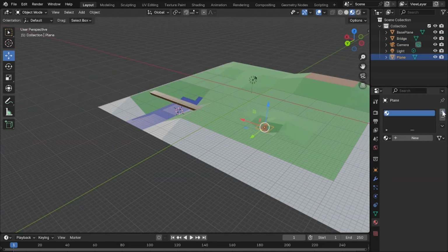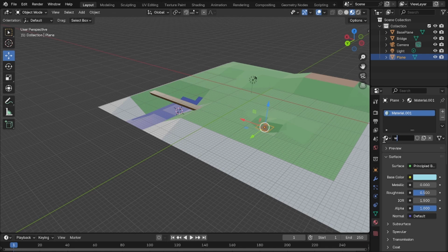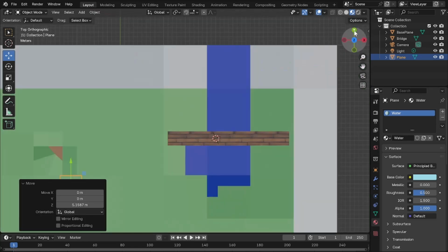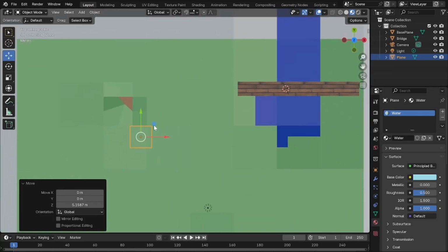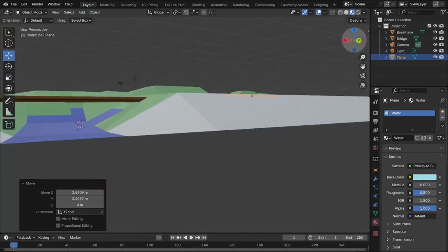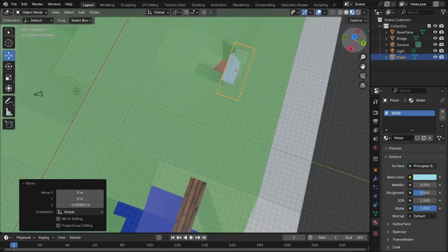Now we've got some depressions, we can fill them with water. A plane is made that lies at a level between the base of the depression and the normal ground level. It should be big enough to cover all of the borders. You'll find that it automatically develops quite a broken up border based on how the land contours round.